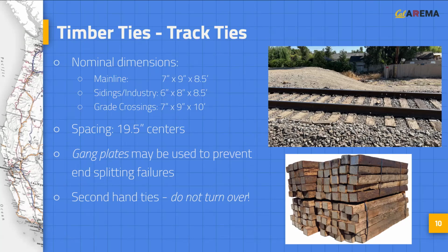There is much debate surrounding the suitability and cost effectiveness of using secondhand ties. If secondhand ties are used, do not turn the tie over, as the previously buried surface will deteriorate rapidly once exposed to air. Instead, make sure to insert the tie as it was originally oriented.